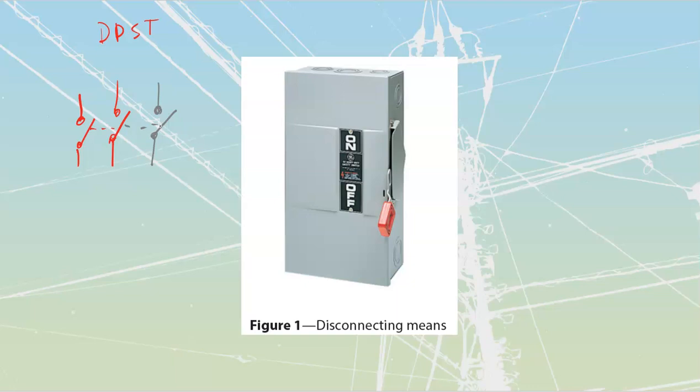We should never have the capabilities that I could just operate this switch on its own, back and forth like that, without having to operate these lines as well. Because if I disconnect, you end up with floating neutrals, and if you remember it all back from first year, if you lose your neutral connection, you run into some massive potentials for unbalanced voltages. We talked a little bit about that this year as well, inside of transformers.